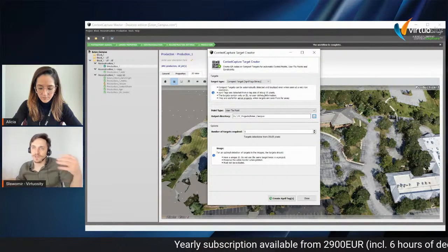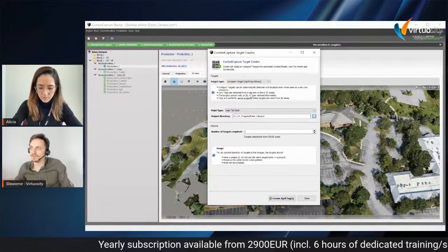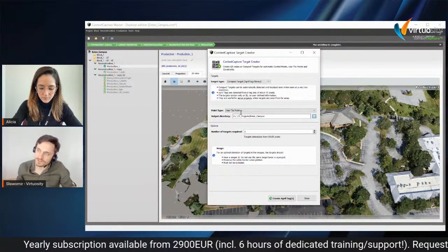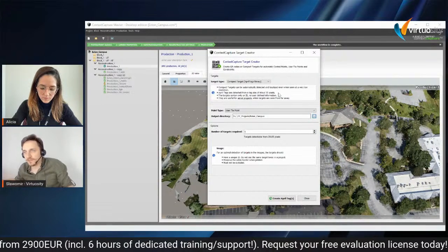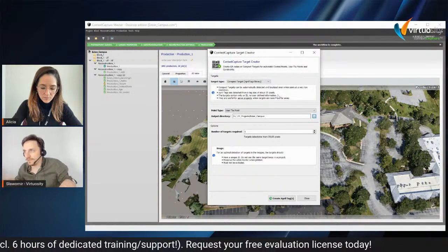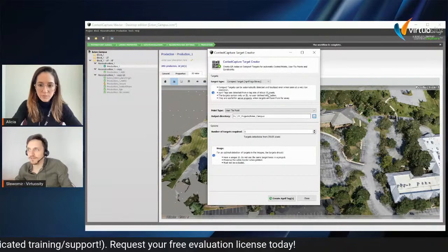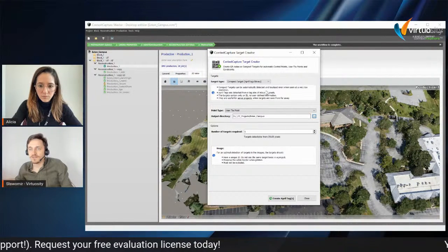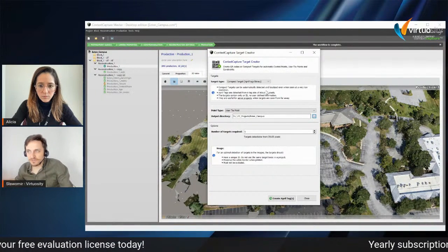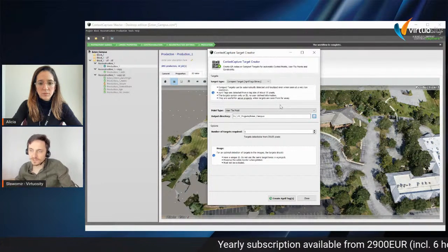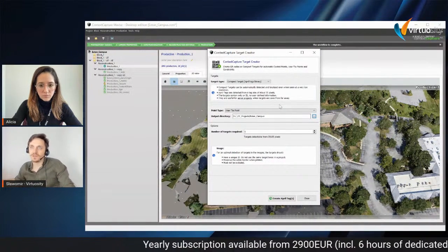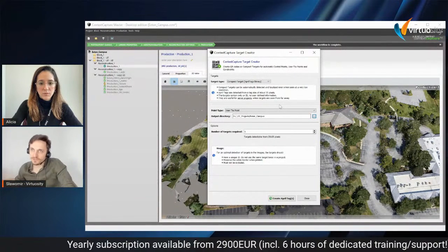In case of aerial photogrammetry, I would suggest to use April tags, because their size in the picture taken by your camera has to be at least 35 pixels. So you have to adjust resolution, calculate the altitude of the drone and compare it with the resolution of your camera.